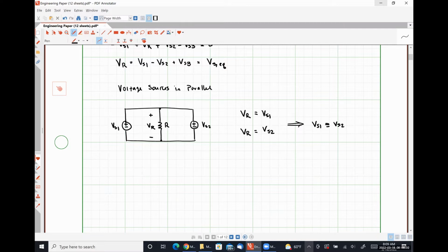The limitation of this model that we're using here is that there's no way for our wires to dissipate any energy, okay? So effectively, in our class, where wires are treated as short circuits, if we have 2 voltage sources in parallel, those voltage sources have to be identical in order for us to proceed and apply our circuit analysis techniques. If the voltage sources are not identical, our circuit theory breaks down and we have to stop our analysis because we don't have the tools in place. Okay. We shouldn't actually see this in any of our circuit analysis problems in this class, but this is a very common practice that's utilized in industry.